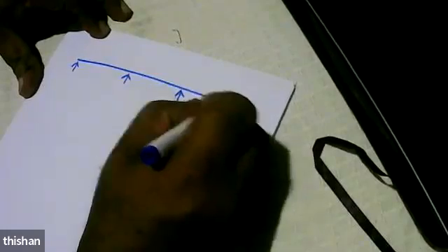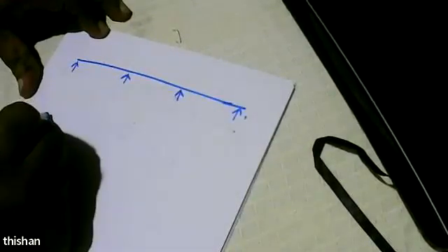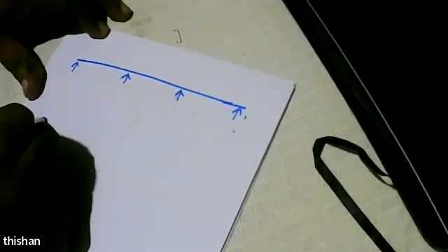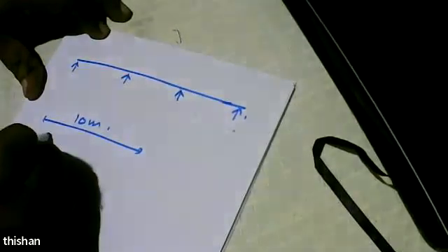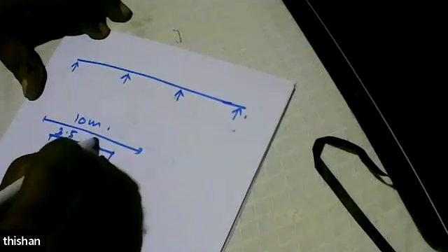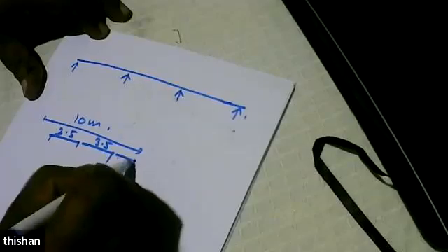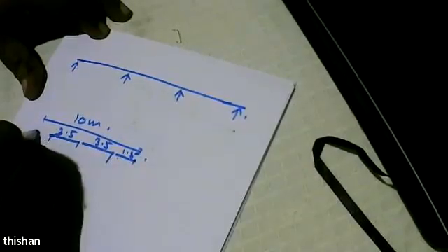What we said was, okay, we have a beam. We have already selected the cross section. How did we select the cross section? Because we know we need 10 meters of flange. Why? Because I am going to have 3 lanes of 3.5 meters each and 1.5 meters for the walkway.